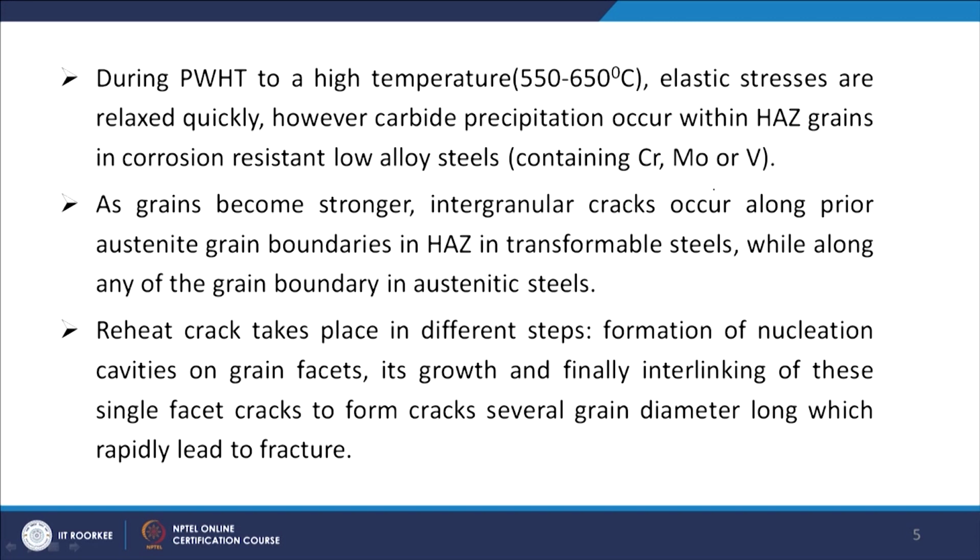This carbide precipitation makes the grain interior stronger, but the grain boundary will be weaker. So your interior will be stronger than the grain boundaries.